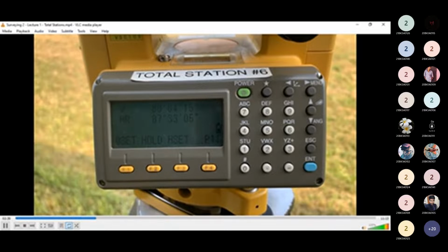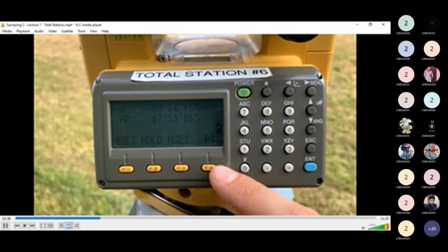When we're surveying using a total station, we're often just using the distance and angle measurement modes, and then star and menu buttons to access some of the features, and the F keys to use some of the features within distance and angle measurement. And we can pair our total station with a handheld computer called a data collector, and that really enhances what the total station can do.